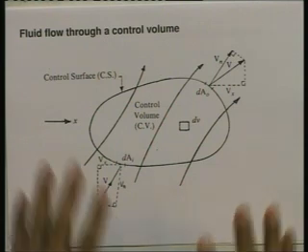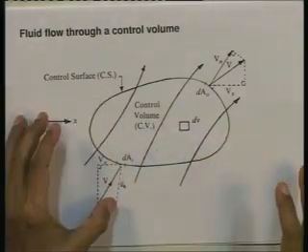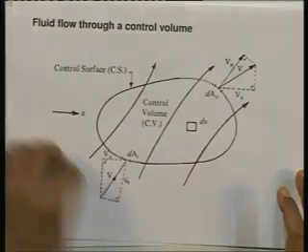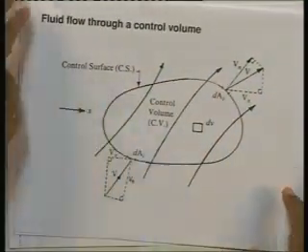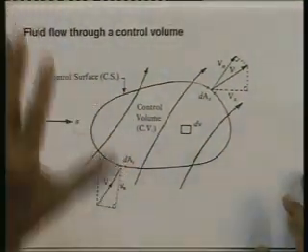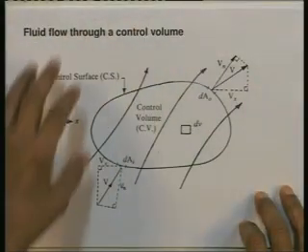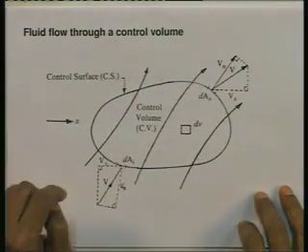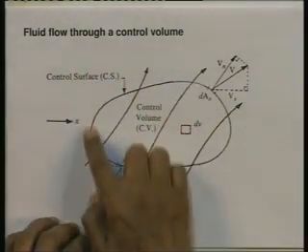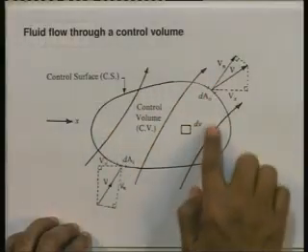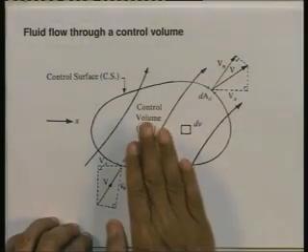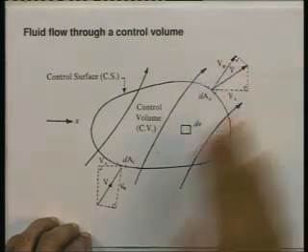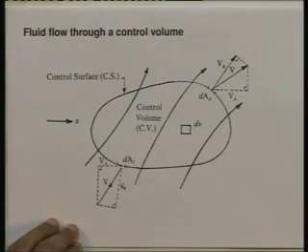It would be: net x direction forces exerted by the surroundings on the fluid inside the control volume. I am giving the equation in one direction, say the x direction. This may be fluid in the surroundings or whatever it is. This is equal to the rate of change of x direction momentum of the fluid inside the control volume, plus the rate at which x direction momentum leaves, minus the rate at which x direction momentum enters.